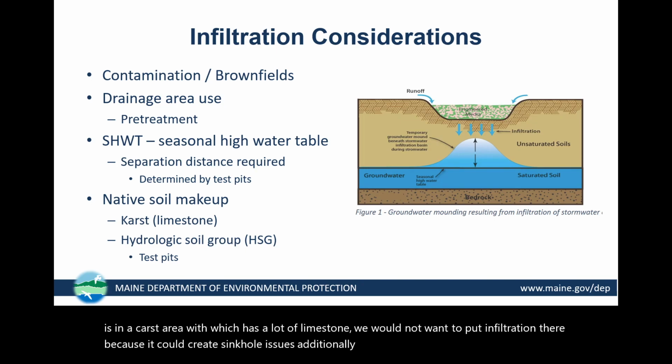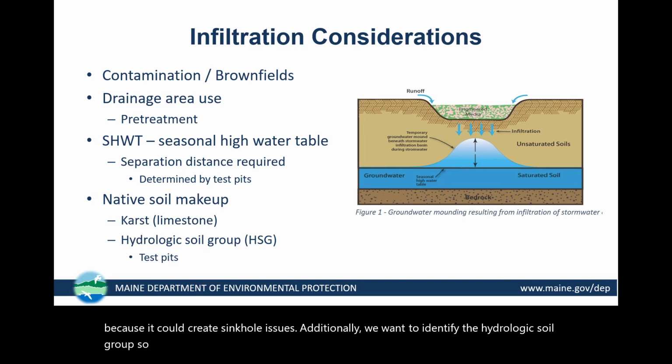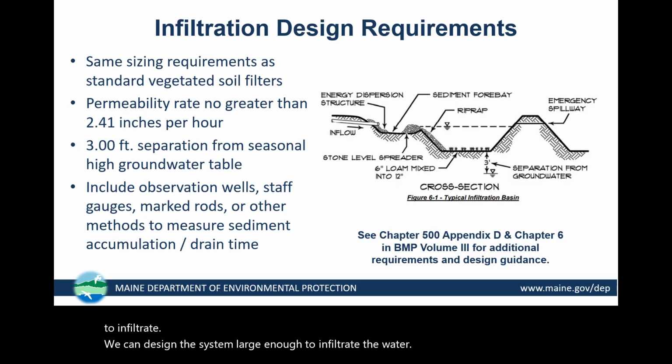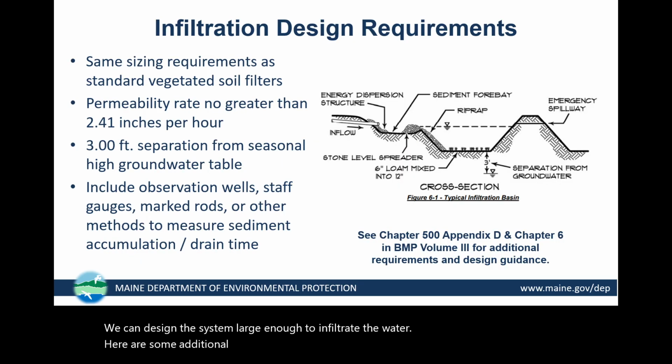Additionally, we want to identify the hydrologic soil group, so that way we know what the anticipated drain time is, and we can design the system to infiltrate. We can design the system large enough to infiltrate the water. Here are some additional design requirements associated with infiltration.